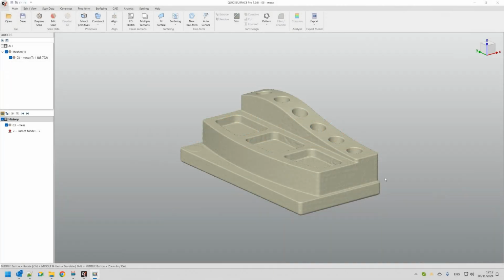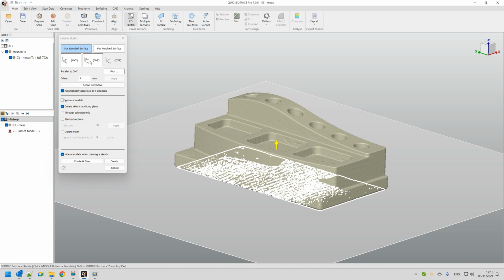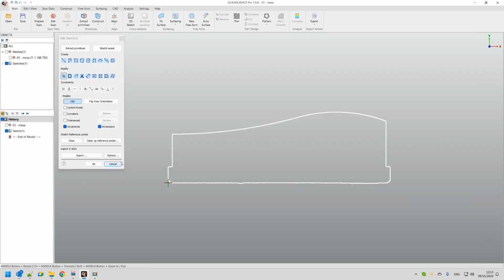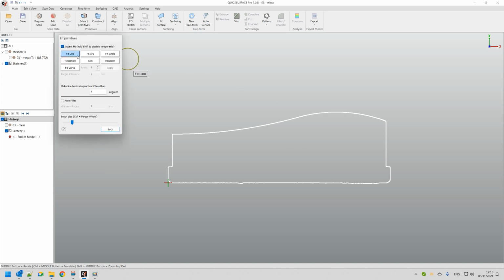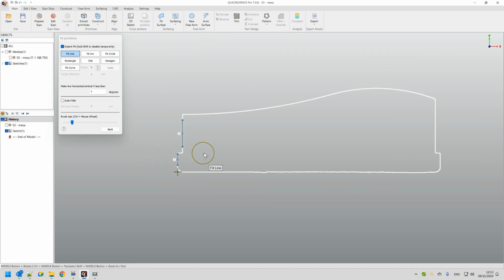The other small features which we introduced are really valuable for the process and make your life much faster, and they are still in the 2D sketch. I can just go now to 2D sketch and extract this vertical shape. This is a complex curve here. I can just create this and accept. And what we have in our new development is that when you extract primitives, together with extracting the lines and arcs and automatic sketching, we have a fit surface command. Actually, it's a fit curve, excuse me.